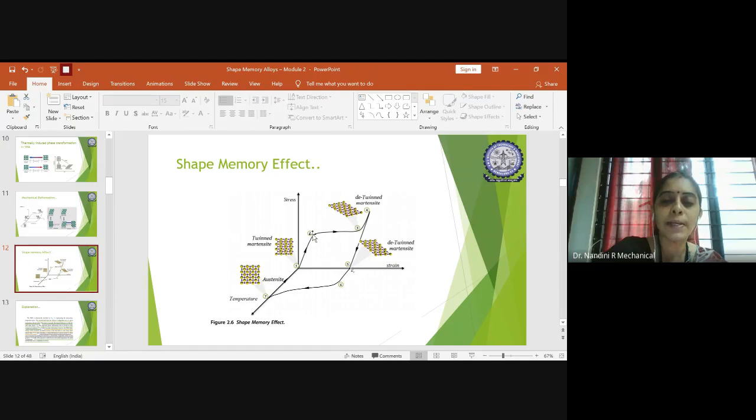So that helps in developing the plasticity nature in the material to evaluate the amount of strain induced in the material, because if you keep on increasing the temperature directly without any soaking time or dwell time, you cannot understand what is happening within the material. So you have to retain some amount of constant temperature. Suppose it is at room temperature here, you will increase the temperature to either 90 or 100 degrees Celsius.